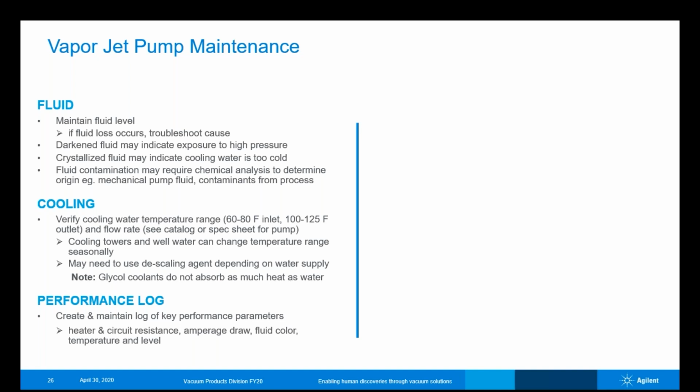We need to be aware that for companies using city water or cooling towers, the temperature of our source water can change drastically from season to season. And we also need to take care of what the mineral content of our cooling water is.